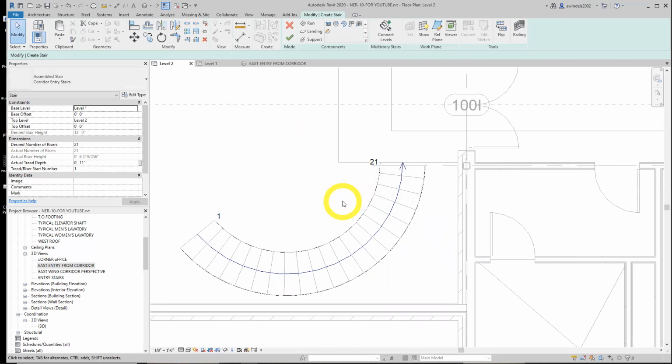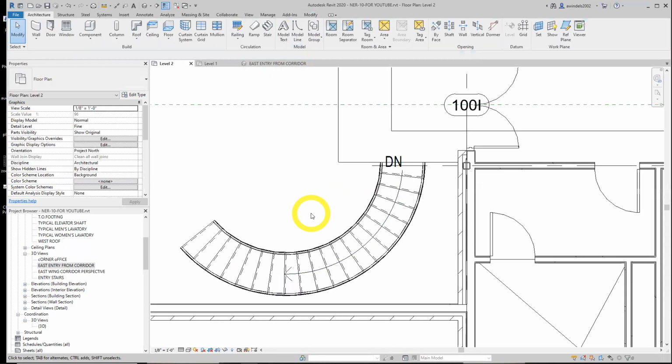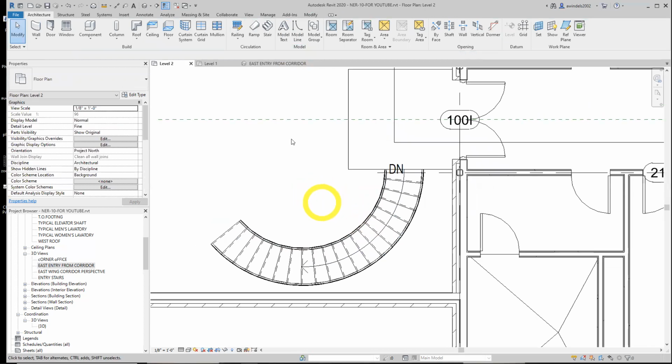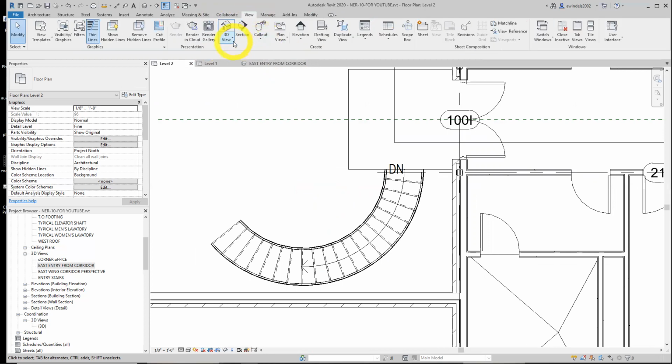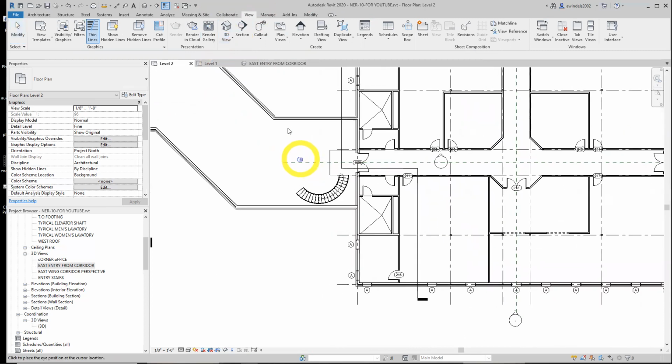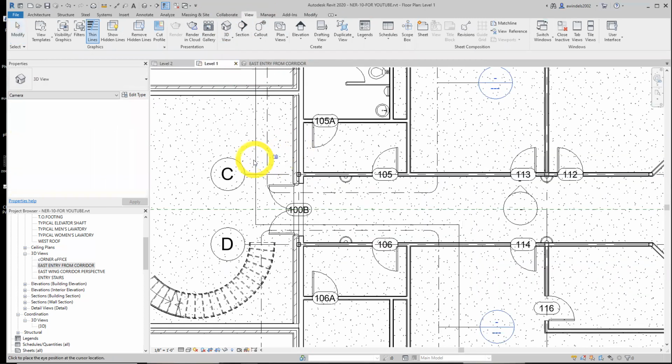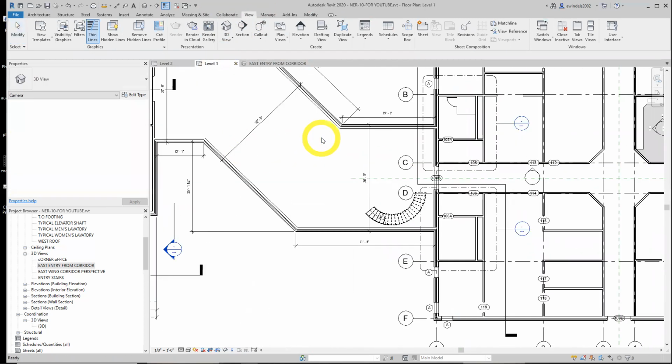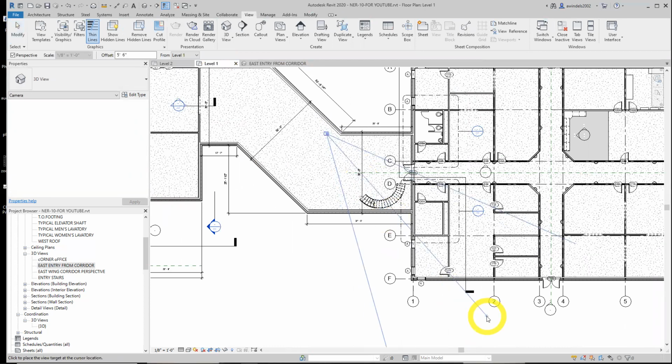It's adding the railing. Can't really see it yet. So hit finish sketch. And now they're on there. Okay, so now you're making this 3D view. Bear with it. Follow the instructions in the book if you want. I already made it by going to view, 3D view camera. I made the view on level 1, looking at the stairs, going this way, selecting it.